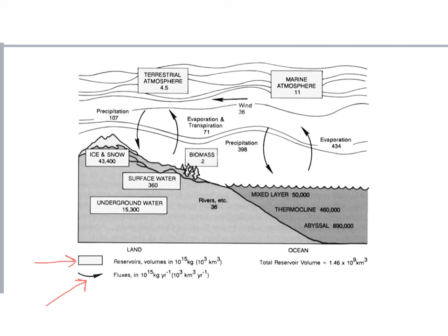So we're going to look really closely at what precipitation means, how it occurs, why it occurs, and then study how to use historic records to predict into the future. We're going to look really closely at evaporation and the dynamics behind how that occurs. We're going to look at infiltration, trying to estimate for each rainstorm how much water is going to actually infiltrate into the ground versus run off and hit our rivers and streams.